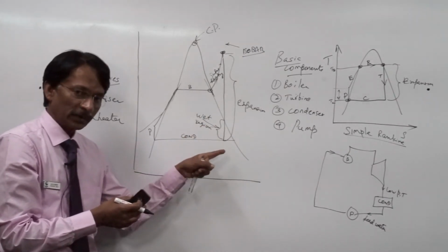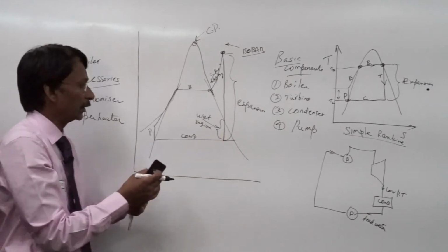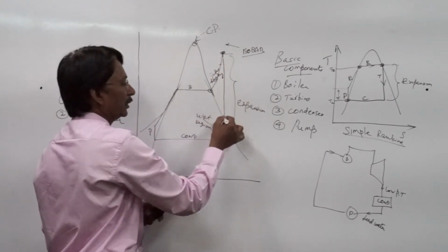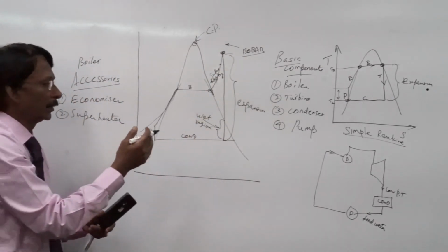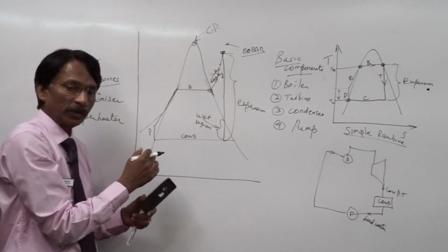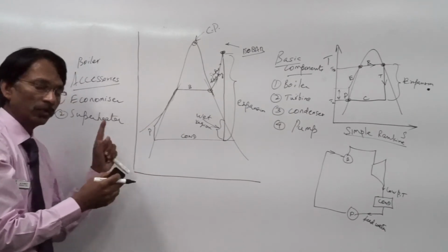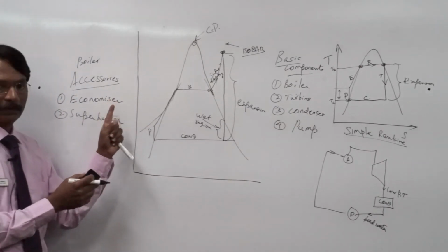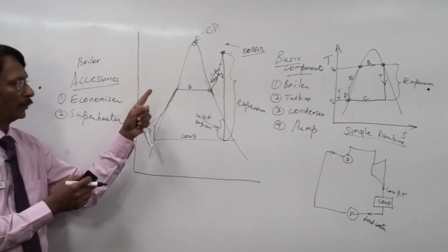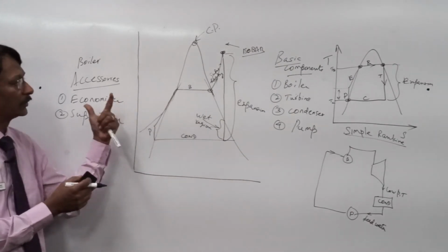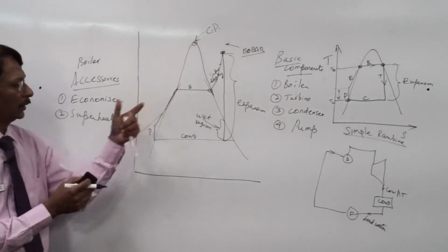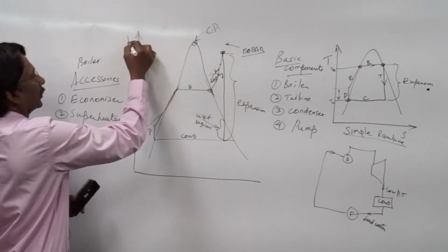There is going to be condensation on the turbine blades, whereas you see here this much of expansion has happened in the dry region or the superheated region. So, this is one of the biggest advantages of superheating of steam. So, superheating is one method by which we are able to enhance the efficiency of a steam power plant, and this is one of the ways we modify a steam Rankine cycle.